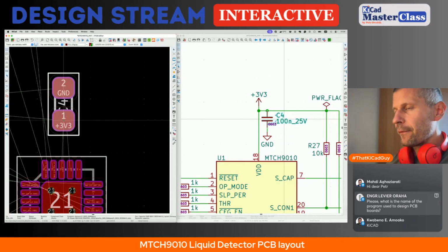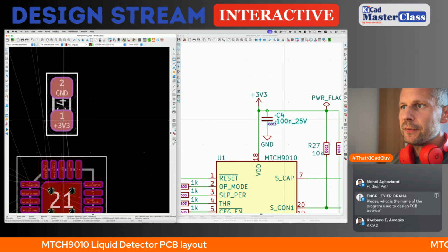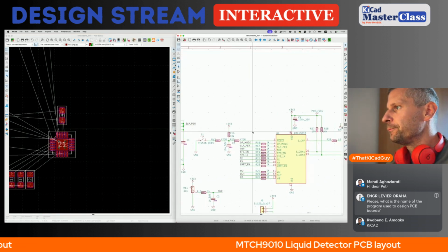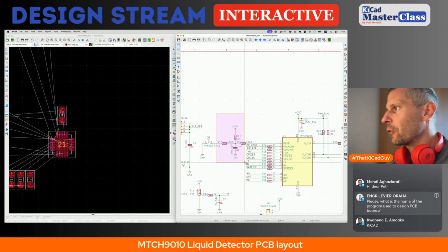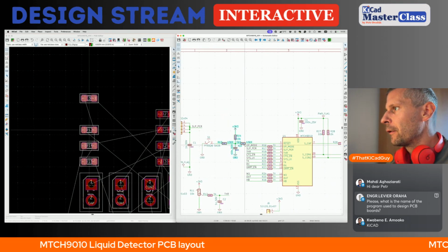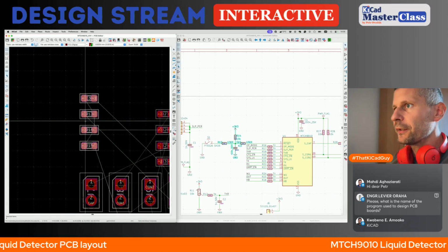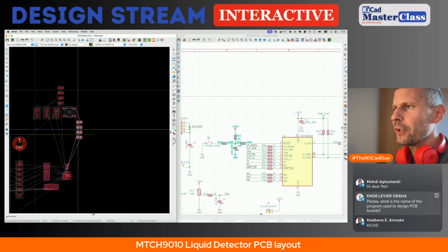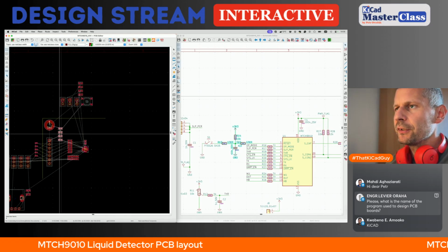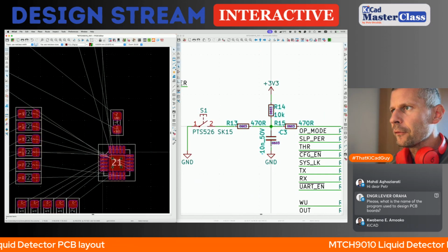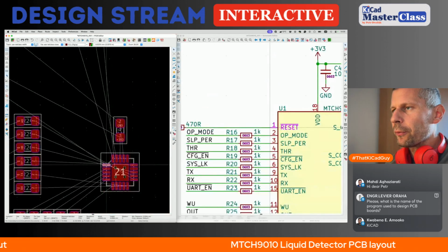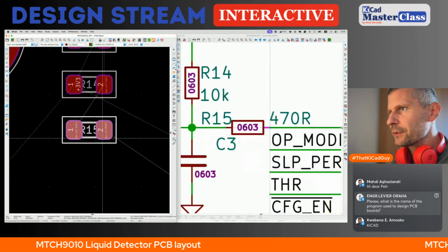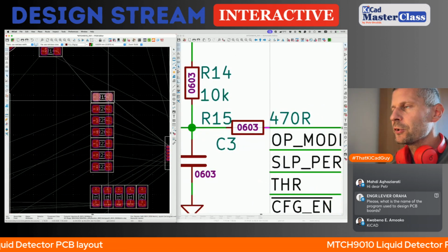The center of the pad is here, like this. Now the bunch of the reset signal components are here for passive components, all coming to the pin number 1 of the IC, which is here in the top left corner of the IC. So it looks like a good position as we chose.